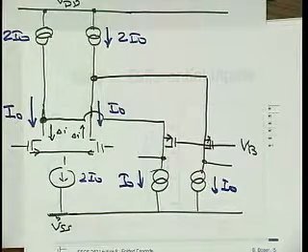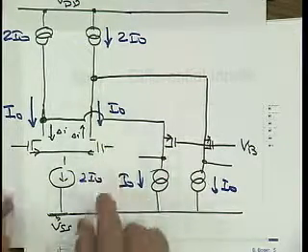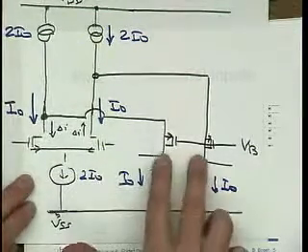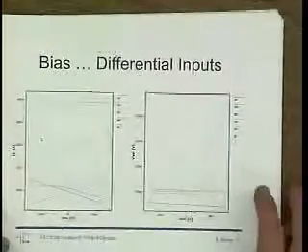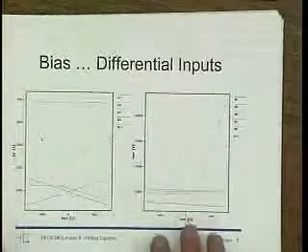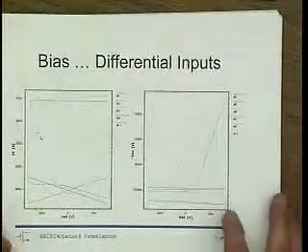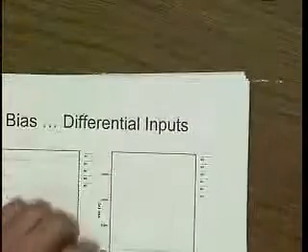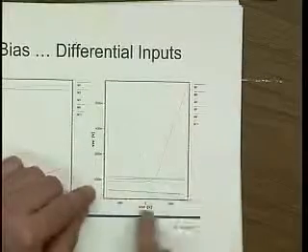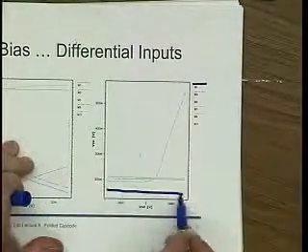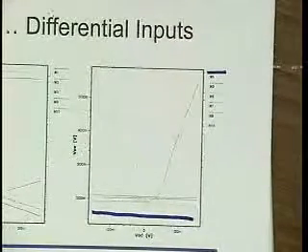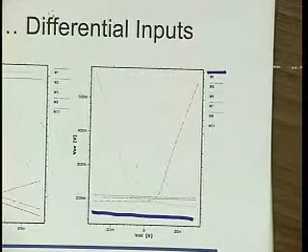And then as you imbalance this, I deviate from this and develop an output voltage. So here I just verify that that's actually the case and that I have the V stars that I like. Notice, actually, if you go and look carefully at this, you will find that this is M1. Here is the V star of M1. The V star of M1 is smaller than the other V stars. Why?